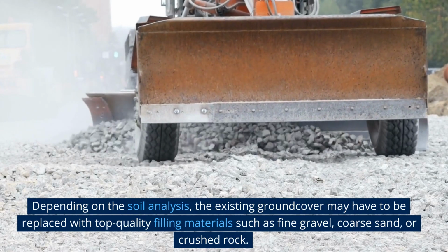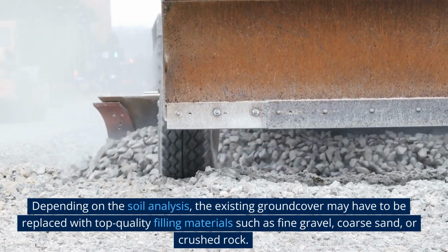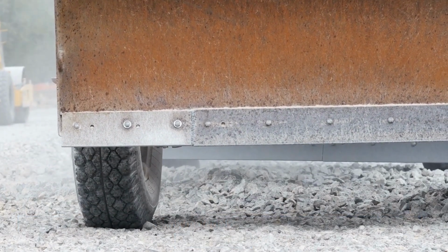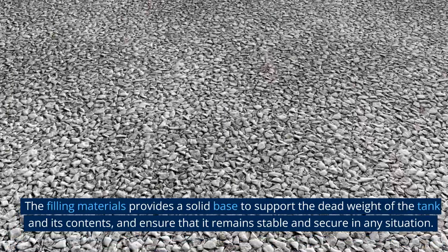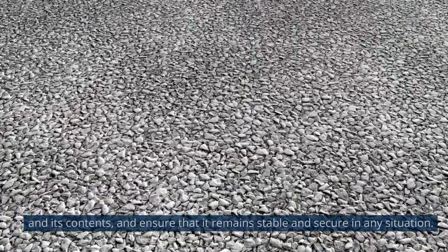Depending on the soil analysis, the existing ground cover may have to be replaced with top-quality filling materials such as fine gravel, coarse sand, or crushed rock. The filling materials provide a solid base to support the dead weight of the tank and its contents, and ensure that it remains stable and secure in any situation.